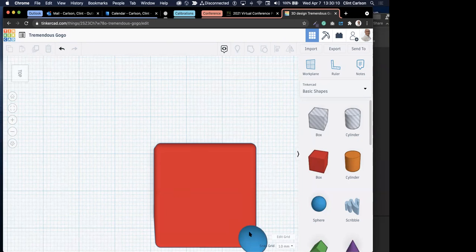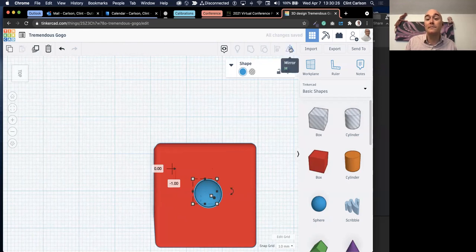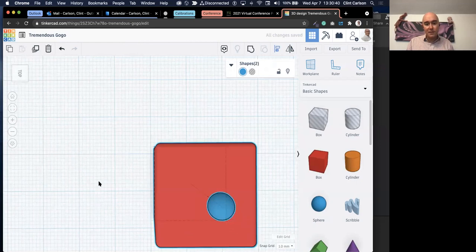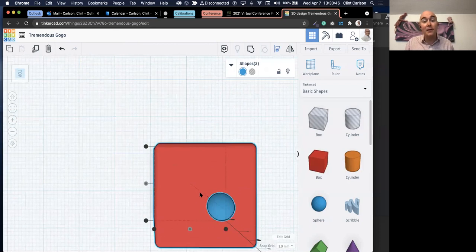Thanks. We're going to grab this ball and try to line it up right in the top. And it gives you these hints. It tells you that I'm 0.7, it's millimeters, if you're curious, and 4 from this side. It does give you these cues to line these up, but there are also these alignment tools up here. So if I select that, hold down Shift and select the other one, I can also grab these alignment options. I can align that just by clicking those center pieces. It's directly above it, and because I've used the align options, I know that it's exactly centered on both sides.